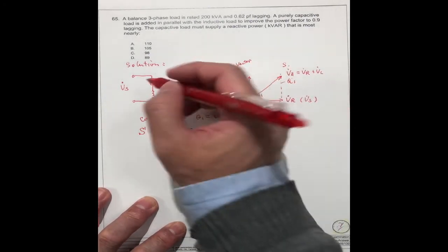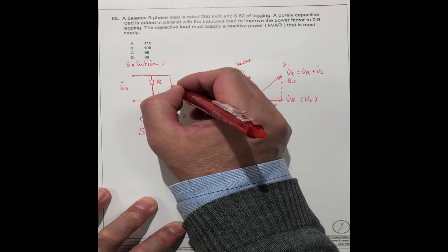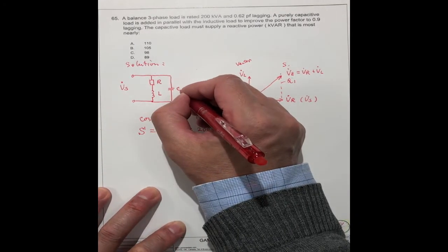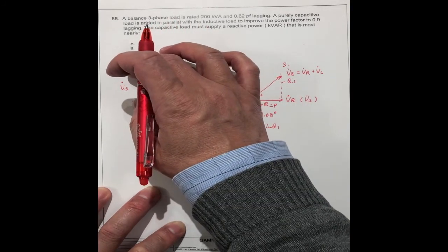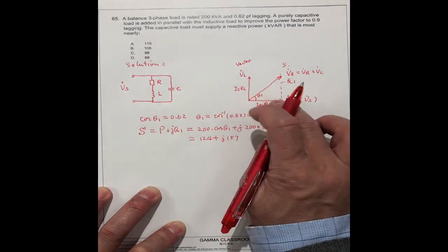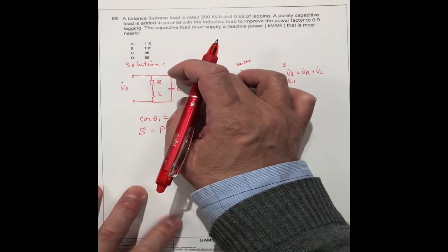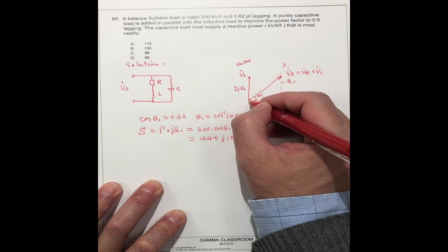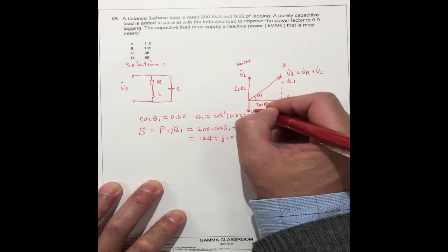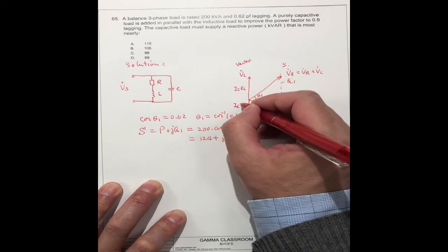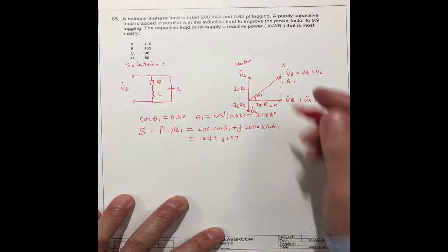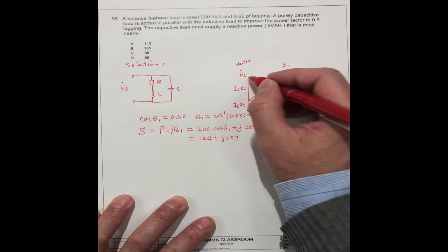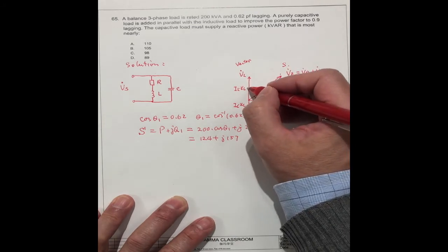Now if we put a capacitor in this circuit, the capacitor C is added across the system voltage Vs. The current is the same, but for the capacitor the current leads the voltage by 90 degrees, so VC equals IC times XC points in the opposite direction. It is totally the reverse, so the reactive component is reduced from the system.